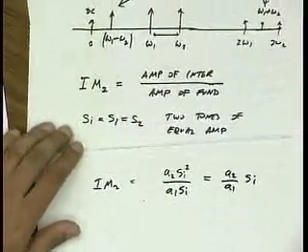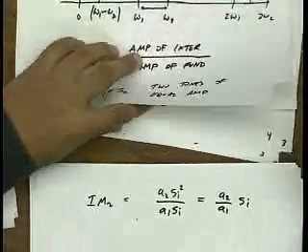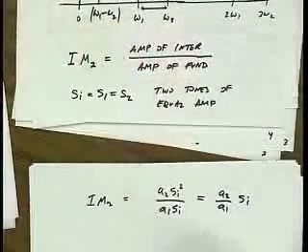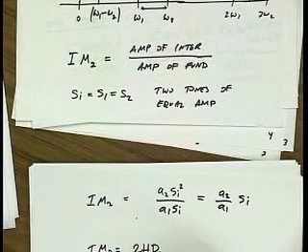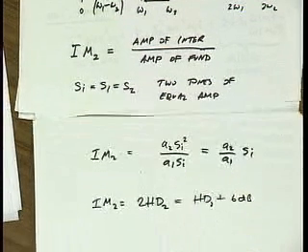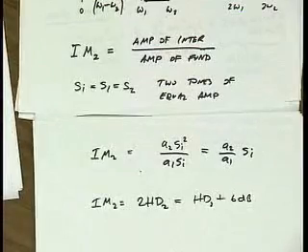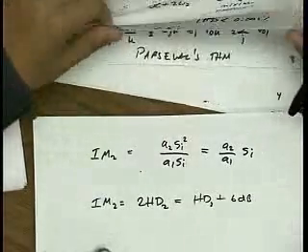And incidentally, this is the same formula that we derived for HD2 with a scaling factor. So IM2 is 2 times larger than HD2. In other words, it's HD2 plus 6 dB on a log scale. Okay? Questions or comments about this?